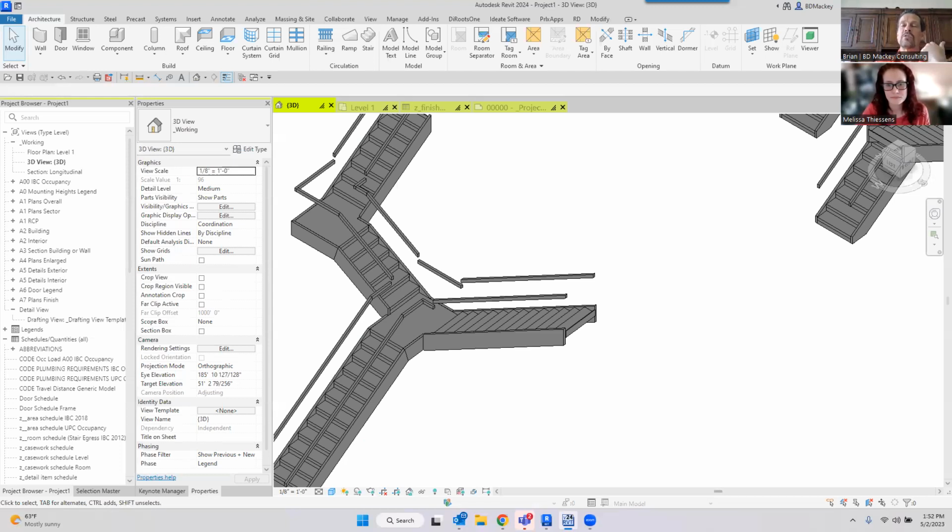is I can start drawing that stuff in any view. So if I go to my systems tab, I can come up here and say, cool, I want to go ahead and just draw a duct. It's going to ask me what size is the duct. I want to start at level 1. That's fine. I really don't want a 12. Why is this grayed out? There we go. I really don't want a 12 by 12. We'll say like a 4 by 4. The reason I have a collector is my collector is face-based.